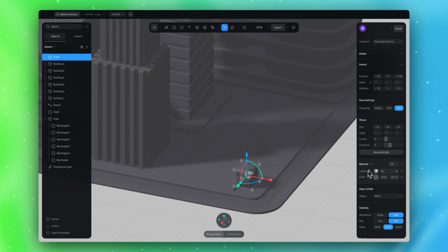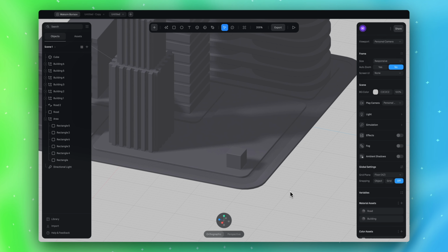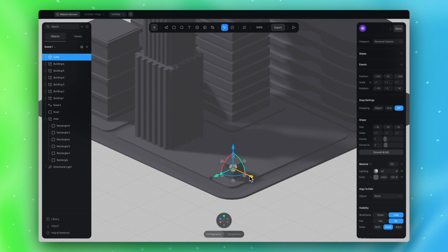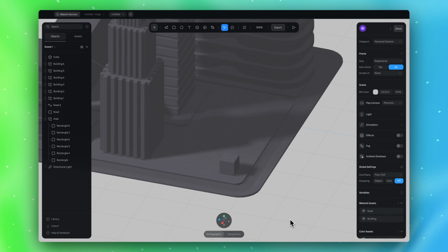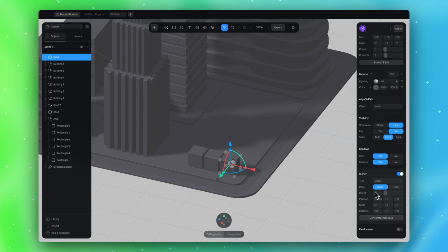Let's change corner radius 1 and corner size I will set 2 in that case, because I will clone this. Every new clone creates some polygons, so 2 will be enough here. Okay, I have a cube. Now let's apply cloner with a grid, because we need to create not just one line, but floors as well.